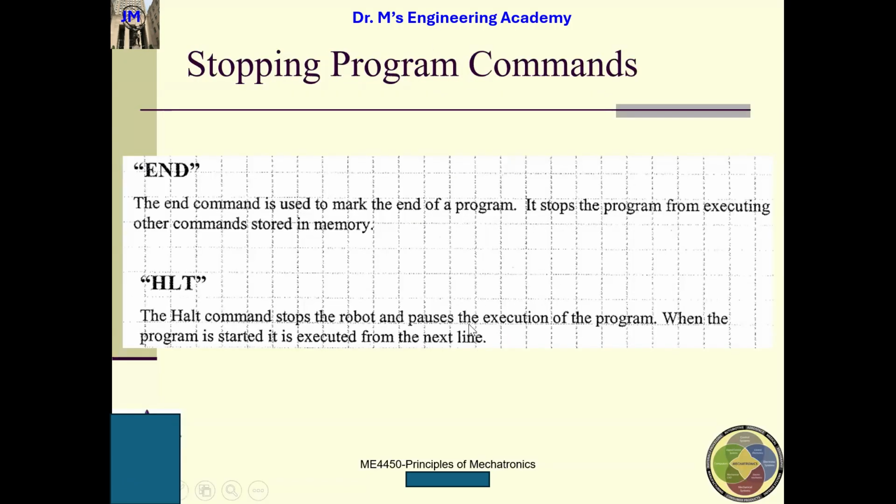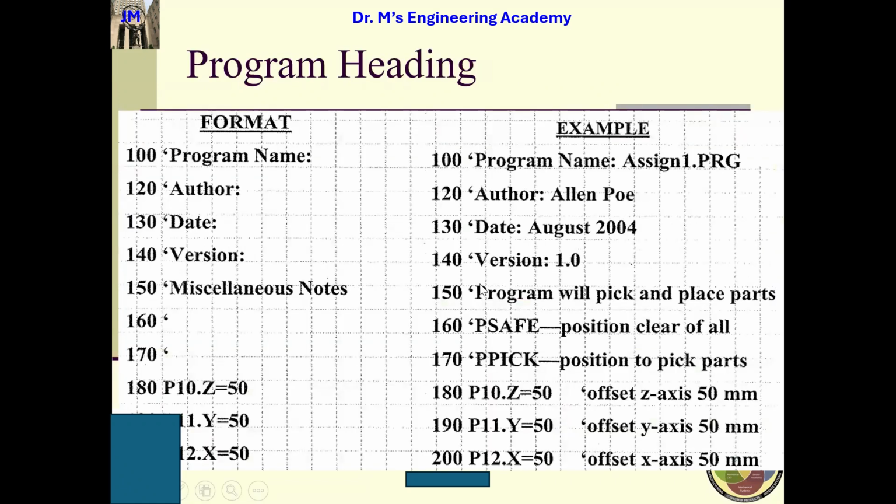Questions so far? No question? So there is a program heading. The program heading is used to improve the readability of your program. Last time I told you, for MELFA BASIC 4 or 5, we use an apostrophe to denote that what comes after it is a comment, and a comment will not be executed.